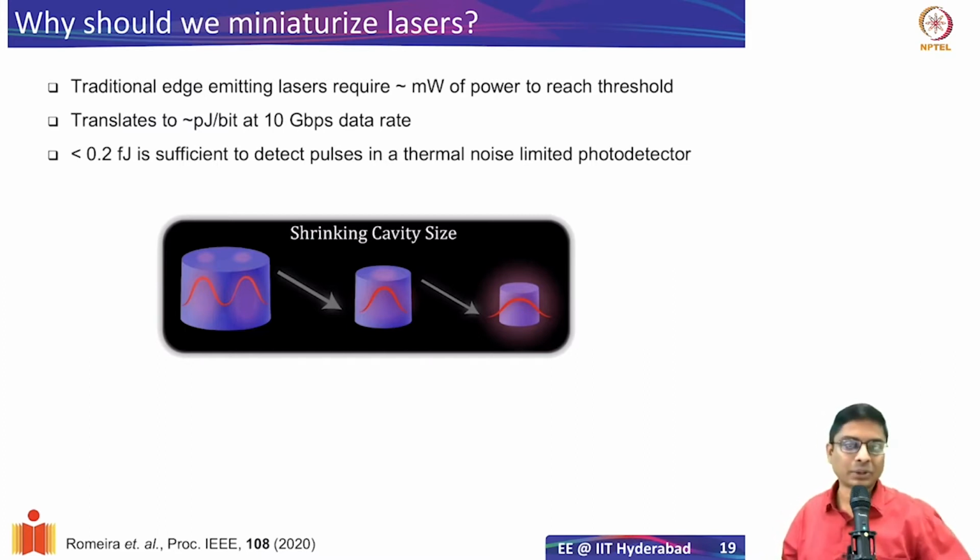So that's a natural question to ask, and that is what I'm illustrating here schematically. So think of the original laser, which had this double heterostructure with two edges. Can I make it smaller? Can I even do away with the mirrors and actually confine my electromagnetic energy in a nano disk like this? We have seen when we studied the Mie resonances, we saw that just a semiconductor disk itself can confine energy, and the Q factor can be reasonably large.